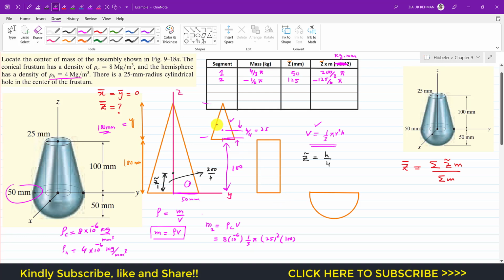Now the third segment is the hole. Again, the material is absent, so we need to subtract the mass of this hole as well. So this is segment 3, and again we need to put a minus sign here. Now the mass of this hole, this is a cylindrical hole. As we know, the volume of the cylinder is pi r square h. Pi r square is the circular area of the base multiplied by the height.